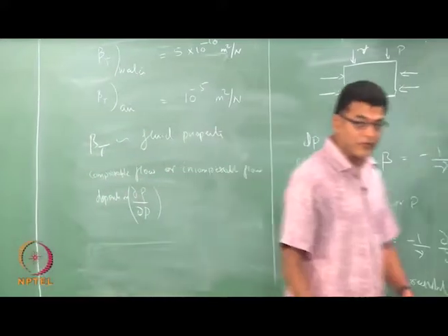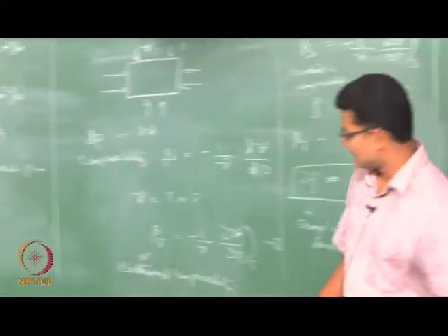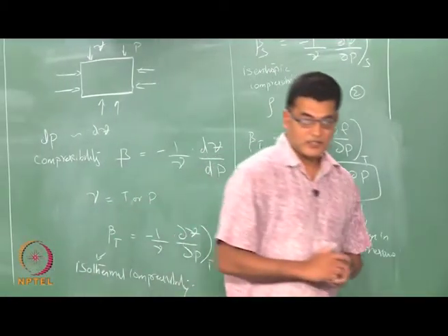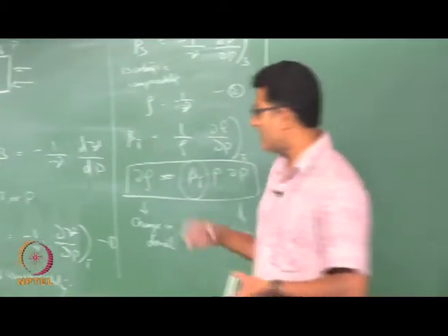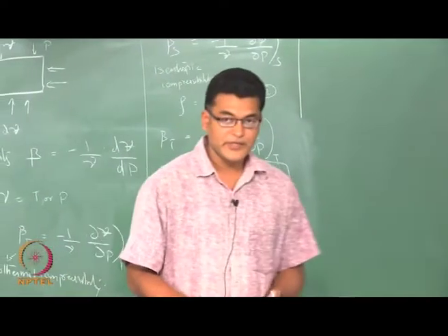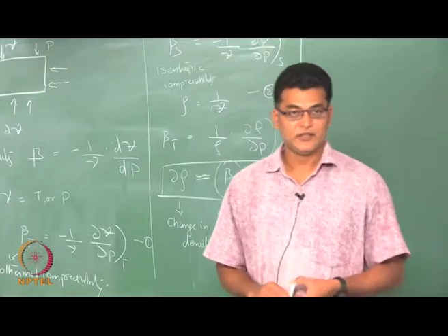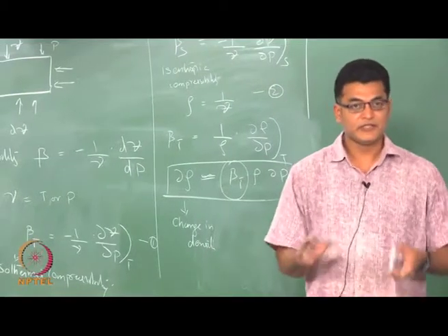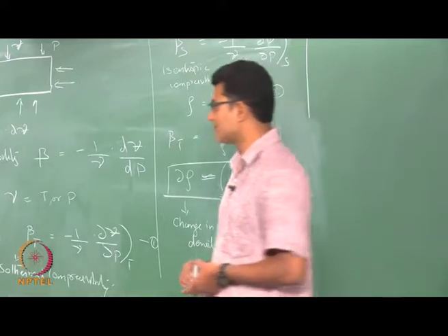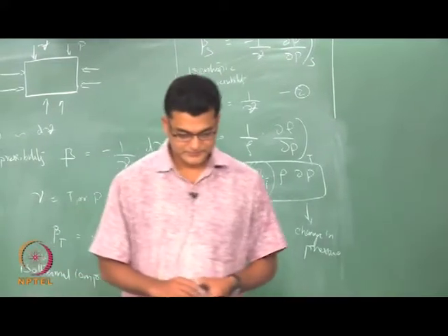Okay. So, the fluid property compressibility is a necessary factor for flow being compressible, but just because it has a large compressibility does not mean that the flow is going to be compressible. Okay. So, the air at very slow speed can still be incompressible. All right.